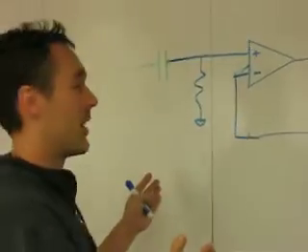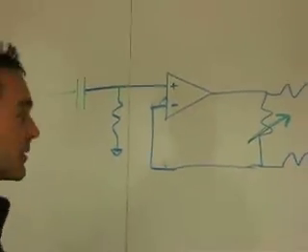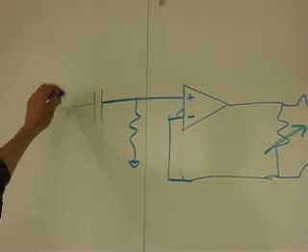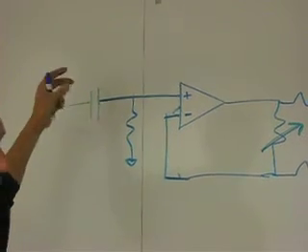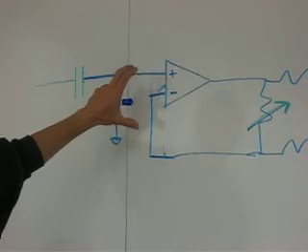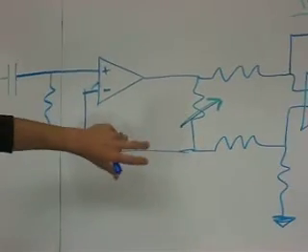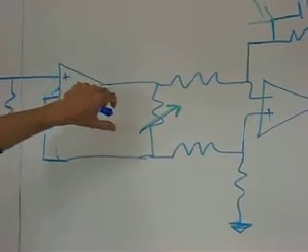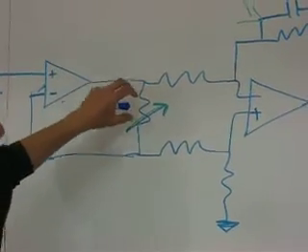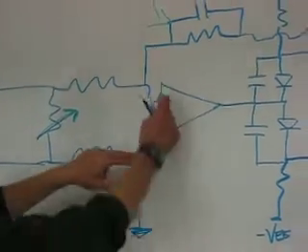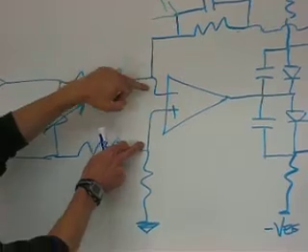We'll go through a brief description of the circuit, and then we will have a little demonstration. So the audio input comes in through a capacitor to eliminate a speaker DC thump, and it goes into a non-inverting amplifier which has the output and the negative terminal connected to a potentiometer to control the gain on the amplifier, and that feeds into a difference amplifier which amplifies the difference between this voltage and this voltage.